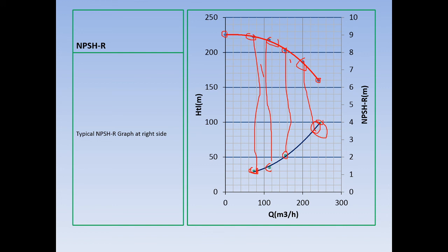It's quite understandable that the higher the flow capacity at the suction, it means the energy given by the pressure from the environment, your 1 bar, you have to transfer into velocity pressure, and then static pressure. So the higher your velocity, the higher your velocity head, and it reduces the static pressure or static head.